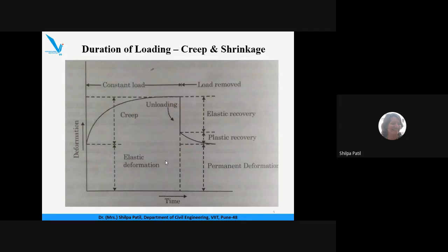Okay, but that is up to a certain limit and depending upon the type of material we are dealing with. Concrete of course shows elastic behavior, but very little, because concrete is not a ductile material, it is a brittle material. So when we apply load on concrete and remove it, it will regain its shape, but only a very small amount. But if we go on applying the load further, the concrete will show plastic deformation. Okay, so this is about elastic and plastic deformation.